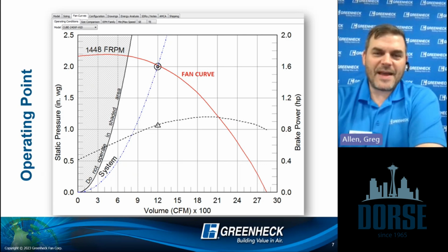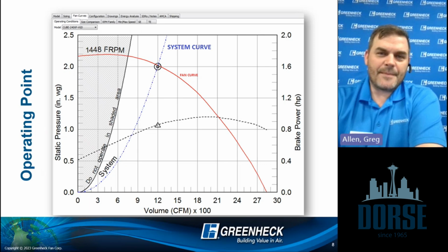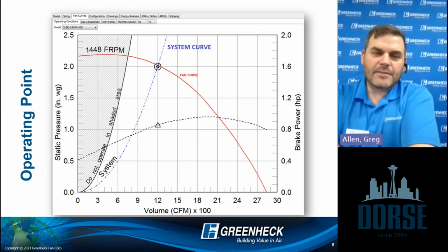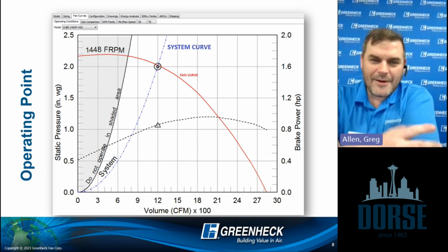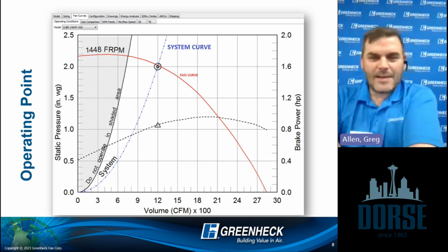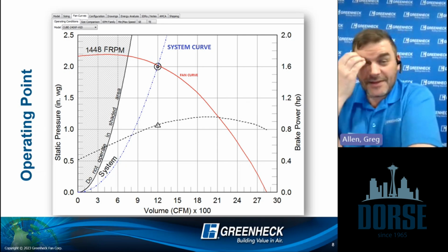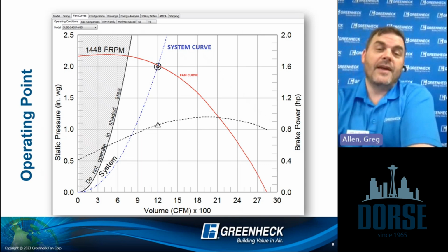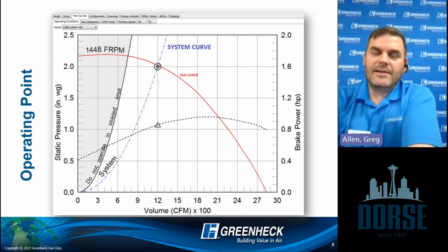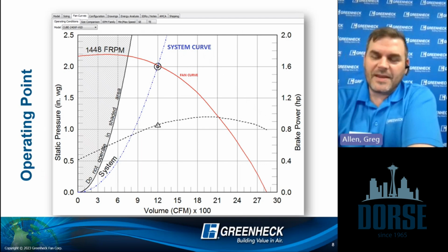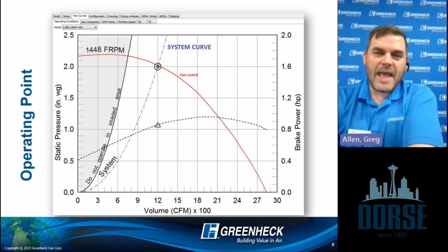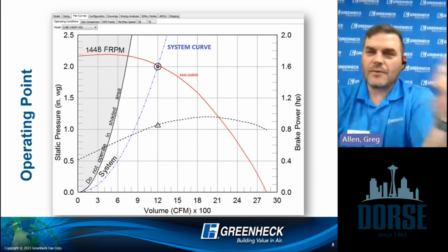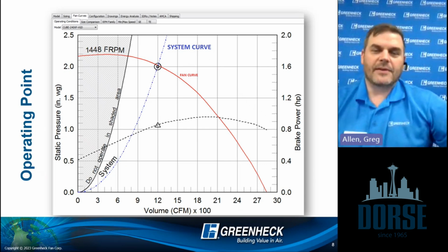All right, so we have a fan curve, which is that red line, our fan RPM, but we also have this blue, squared-looking parabola, right? And this is the system curve. This represents all the ductwork, the 300 feet, the 6 elbows, the reduction, all that has been added up. How much system resistance is going to be added to the system to overcome in this entire system?